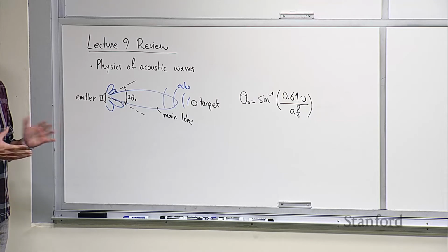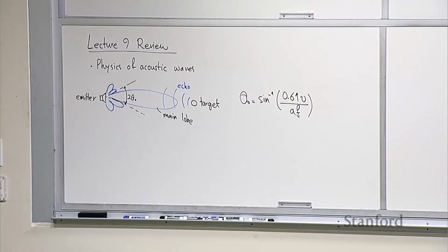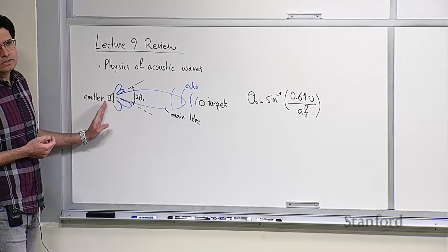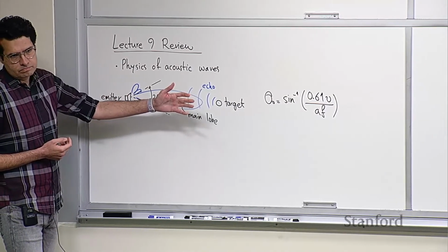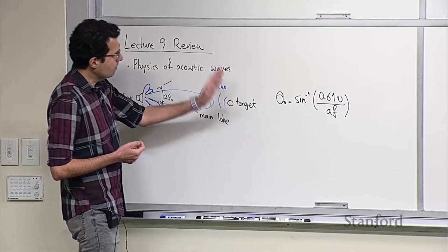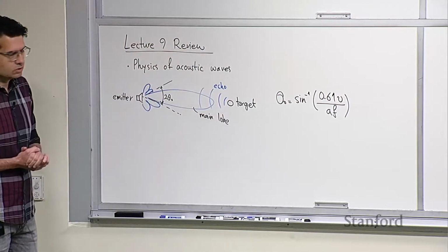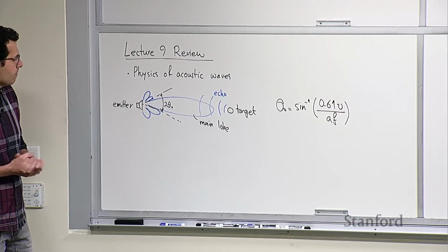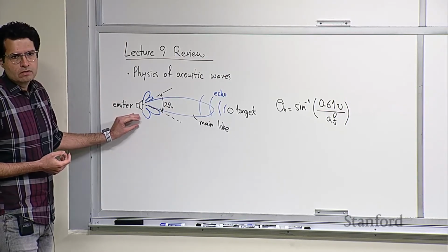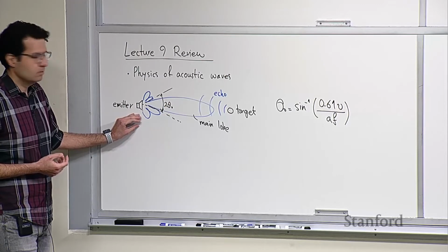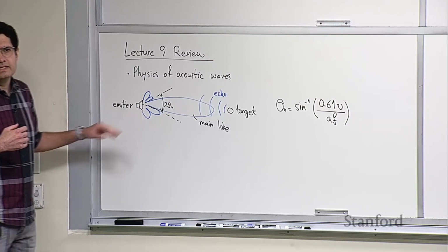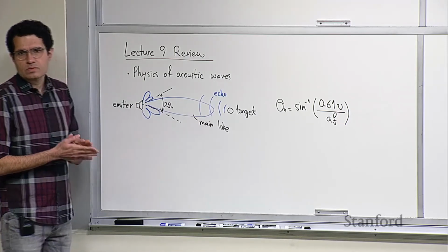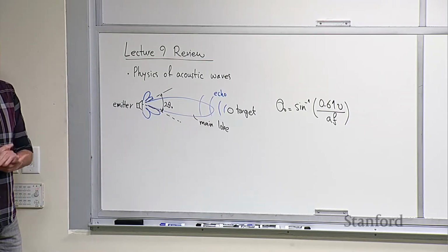studying, and specifically sonar, is a very simple principle. So basically, you have a transmitter or an emitter that sends out a signal. A signal goes into the environment, it hits the targets or different parts of the environment, and some echoes reflect back. And then the receiver part of the sensor collects those echoes, and then it needs to process them somehow and determine the range to each target as well as the bearing angle or direction of arrival to each target.